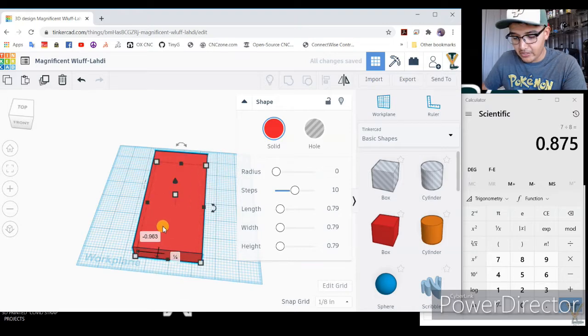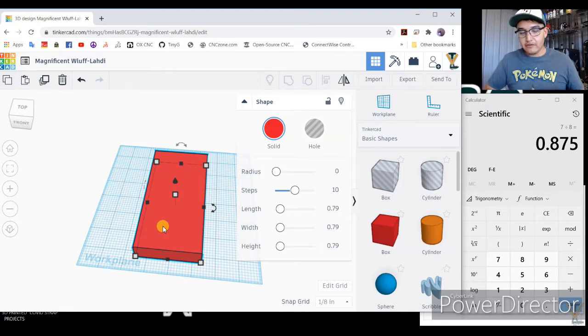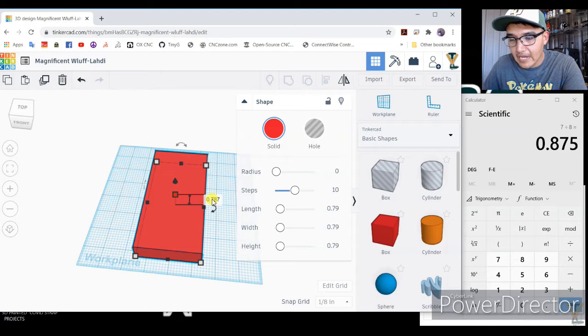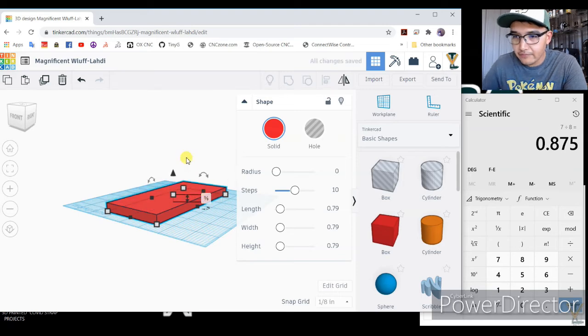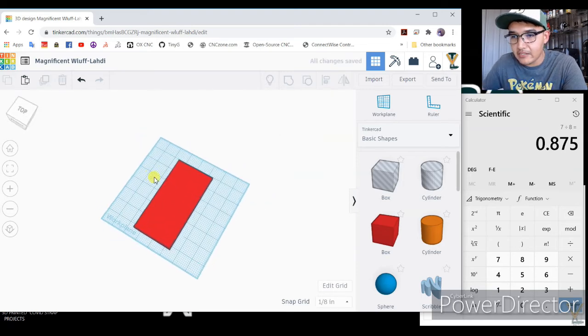So now as you can see here, you gotta make sure that in this area you can fit your cell phone. So you gotta see how thick you're gonna make your case. In this case, I'm just gonna measure my phone real quick, and it says that it's about 3/8 of an inch. So I'm going to change the height, that thickness, to 3/8. In decimal numbers that is 0.375. Enter, and there you go. That's your basic shape. That's the basic shape that you're gonna do.